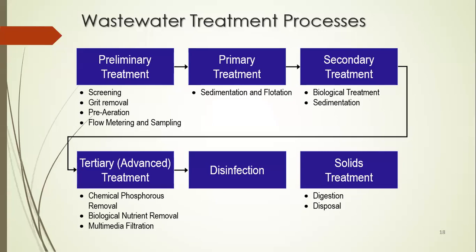The final step of treatment is disinfection. That is removal of pathogenic components from the wastewater. Then finally, you will have to look at the treatment of solids as well, because in the treatment process, you will create solid waste as a byproduct of treatment. So finally we have to look at the solid treatment through different techniques such as solid digestion.